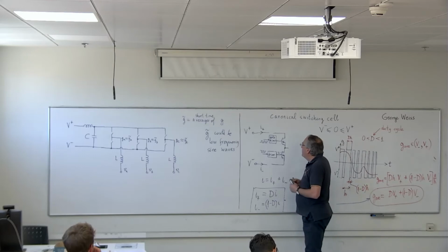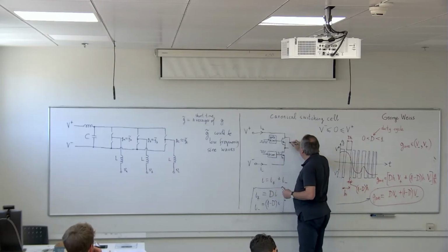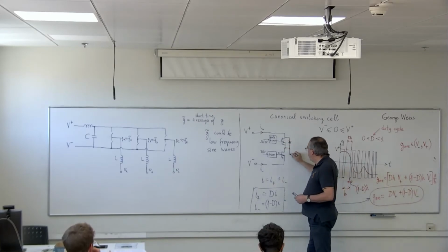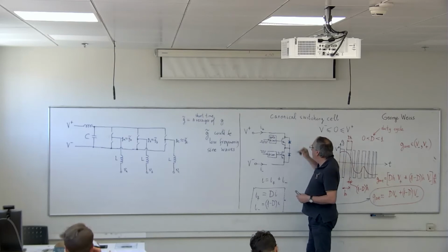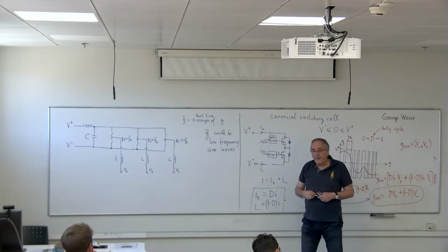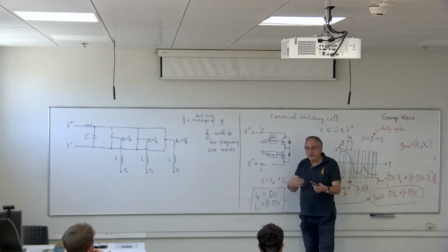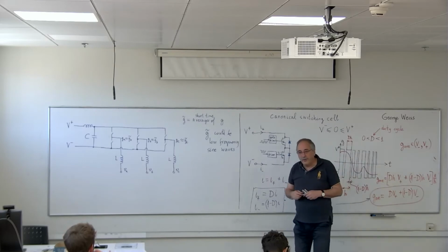And then something else that I should point out is that here you have a diode. And this diode is called the body diode of this MOSFET transistor. You have it also here. And this diode is something that's unavoidable. It is part of the MOSFET transistor. So you cannot avoid it. It is part of the construction of the MOSFET transistor.